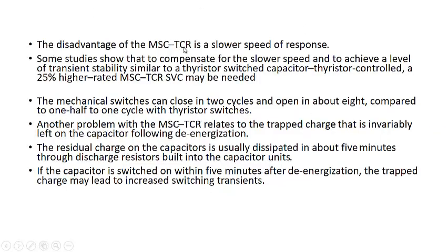The disadvantage of this is a lower speed. That is, the mechanically switched TCR has a lower speed of response. Some studies show that to compensate for the lower speed and to achieve a level of transient stability similar to that of the thyristor switched capacitor, thyristor controlled reactor, a 25% higher rated MSC TCR SVC may be needed.